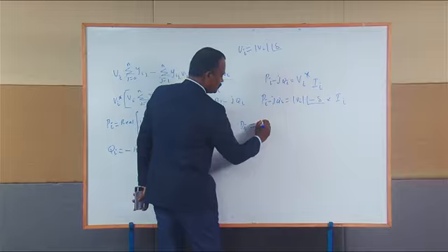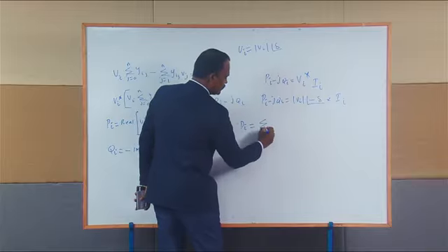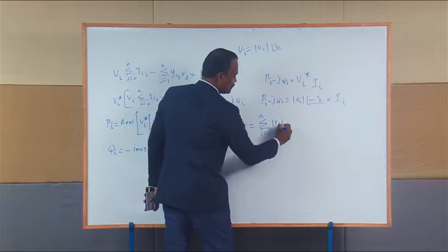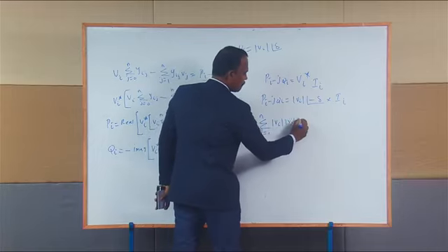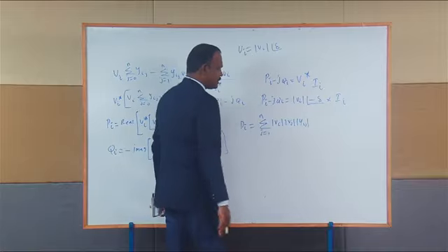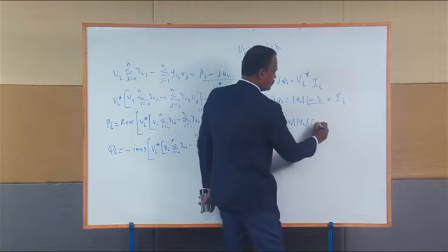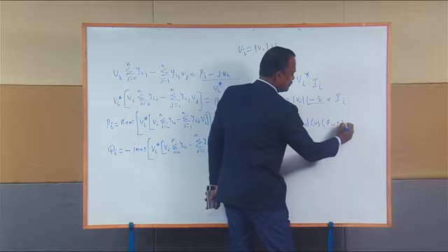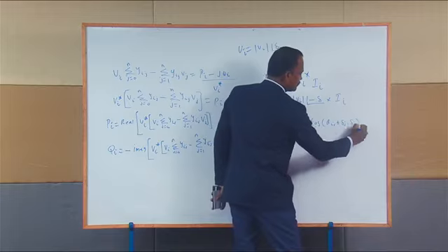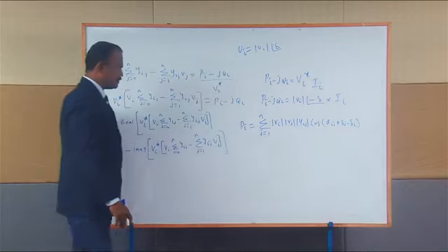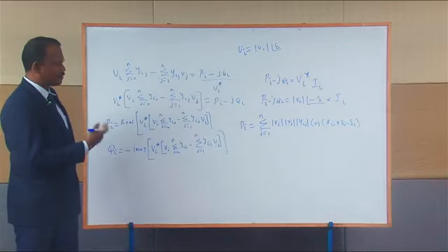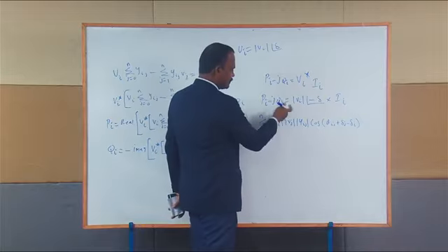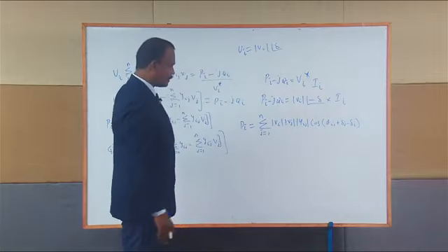Now I can write the same power flow equations in polar form. My Pi is equal to sigma j equal to 1 to n, modulus Vi Vj Yij cos of (theta ij plus del j minus del i). Okay, so this is the equation for the real power in polar terms, because I converted this rectangular equation into the polar equation.